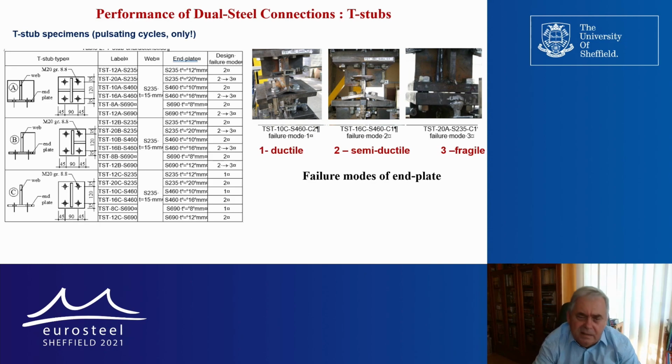The problem with the ductile mode, which is very good in terms of ductility, is that it is very deformable, and we can always have only partial strength connections, which are not accepted in moderate and high risk seismic prone structures.